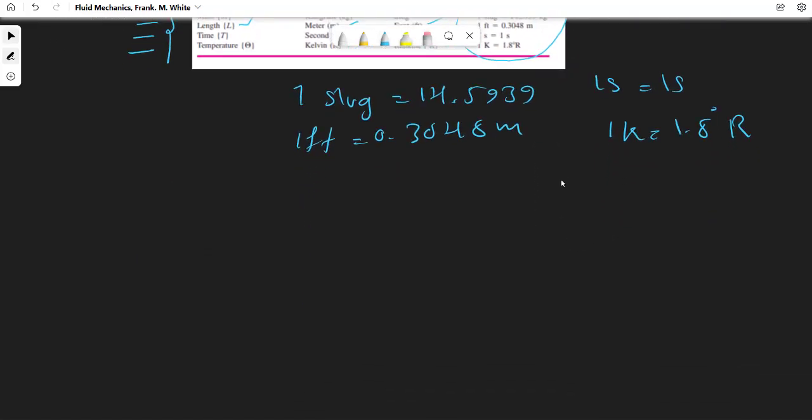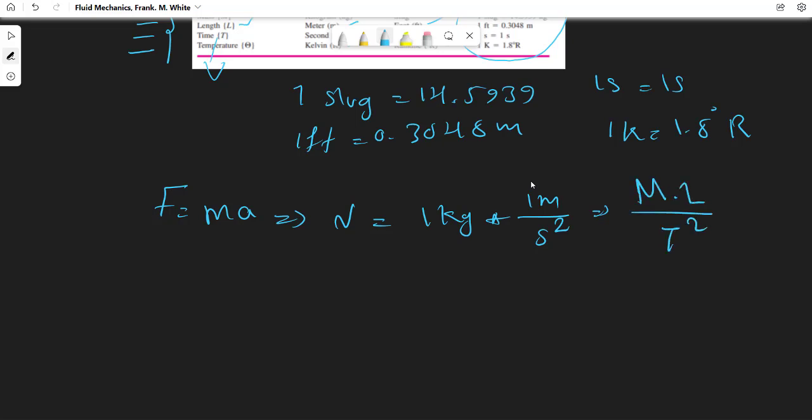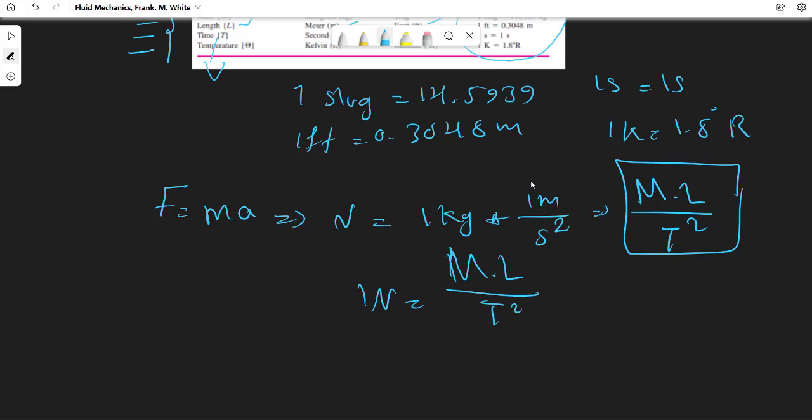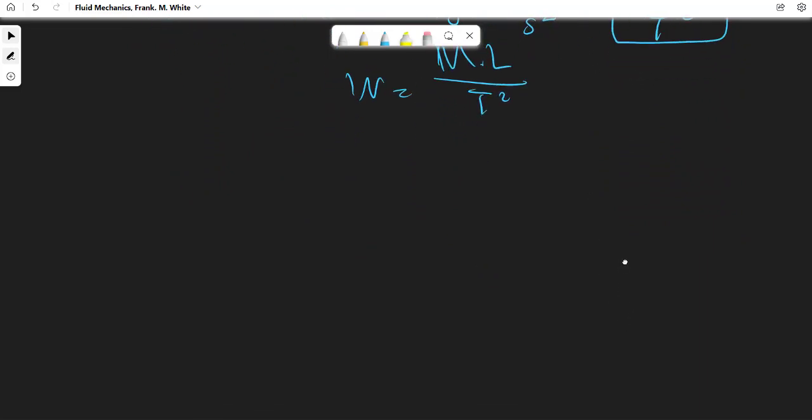Each parameter in engineering has a dimension, and it is useful for checking the answer of a problem, for example, checking the accuracy of the given data or the desired result data. For example, for the force, we have F = ma from Newton's second law. So 1 Newton equals 1 kilogram multiplied by 1 meter per second squared. With this, the dimension is M for mass, L over T squared. This is the dimension of Newton: 1 Newton equals M L T^-2. When you calculate a force, you can check your answer with dimensional analysis.